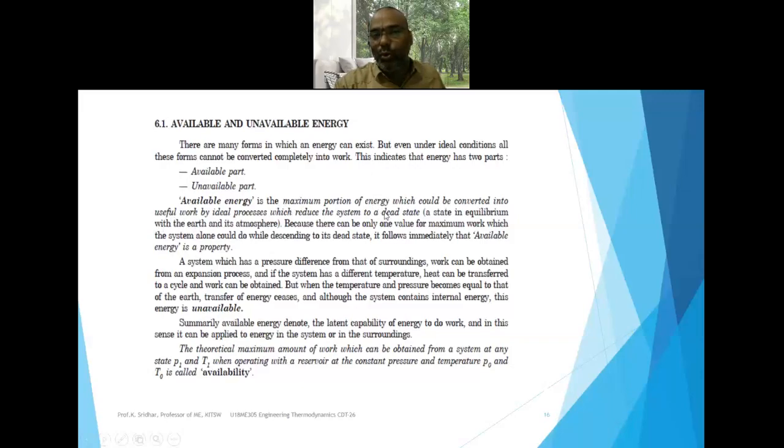That is, whenever we are giving some Q1 amount of heat to the heat engine, out of that Q1 heat input, the heat engine should be in a position to convert it into the maximum useful work by dissipating the least amount of heat rejection. We cannot avoid the heat rejection, but its value should be minimized because W is equivalent to Q1 minus Q2. Whenever the Q2 value is lower, we automatically have a higher amount of work done. So W max is equivalent to Q1 minus Q2.